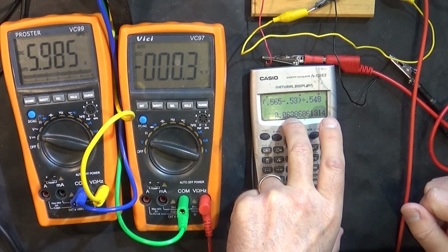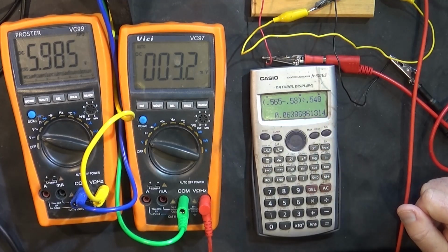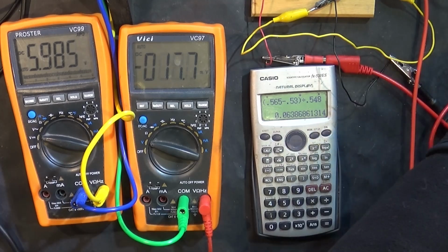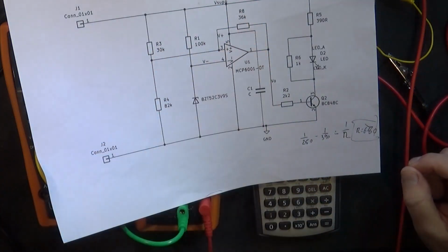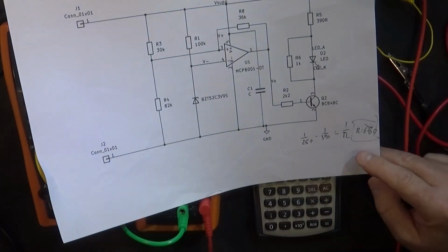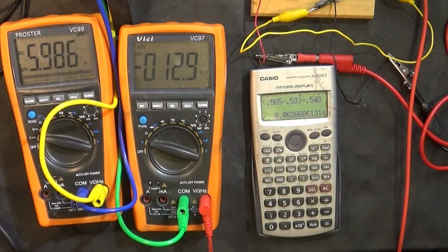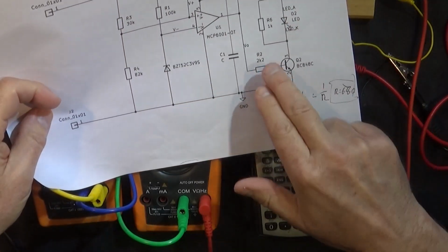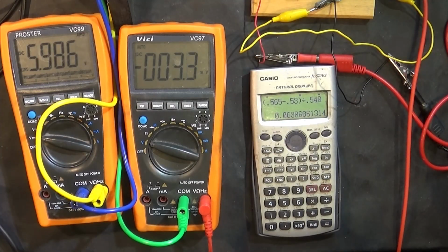error, which is a bit more than we had with our original diode, but it's fine and it doesn't go all that range, so it's probably nearer 5% over the range we're using, which is good enough for what we're doing. Right, so now I need to change those 3 resistors to reflect the new reference. Oh, and I've shorted out here the base of the transistor just so it doesn't turn the LED on, just in case that confuses the issue. So I will fire the soldering up and make those changes.